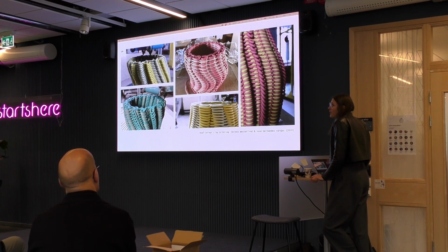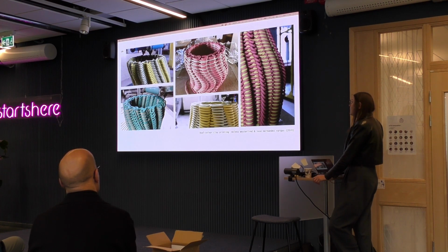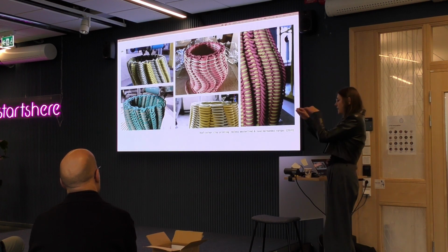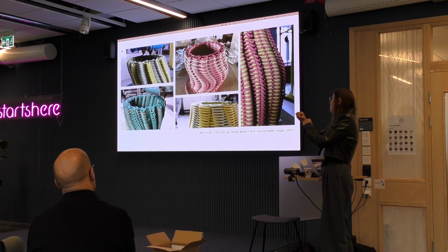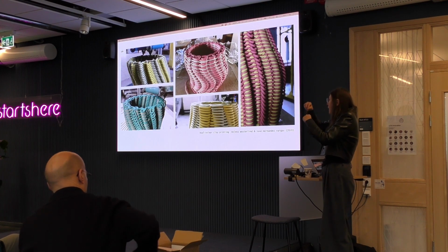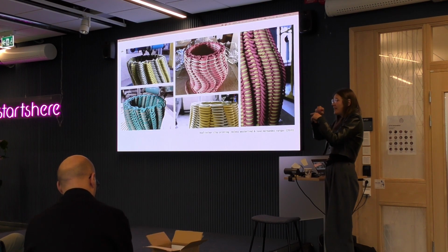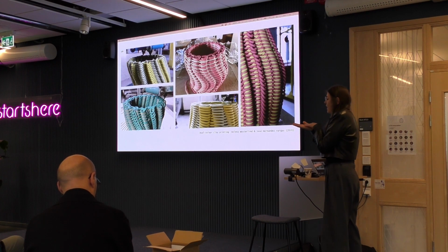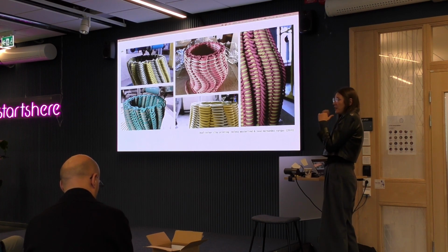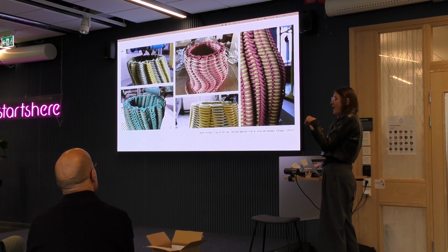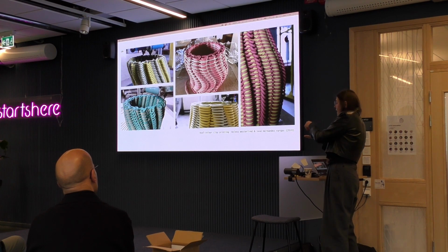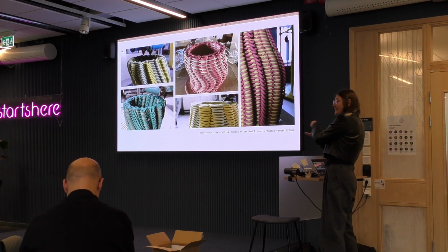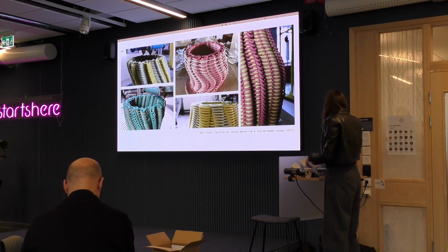While we were down there, we also realized that because we did dual extrusion, the leftover material from one extruder was soiling the next layer. So we took one of those nail brushes and put it next to the machine, and then also added this line in the code, so in between each layer, the head goes to this little brush and does this little movement to clean itself, and then goes back and continues with the next layer.